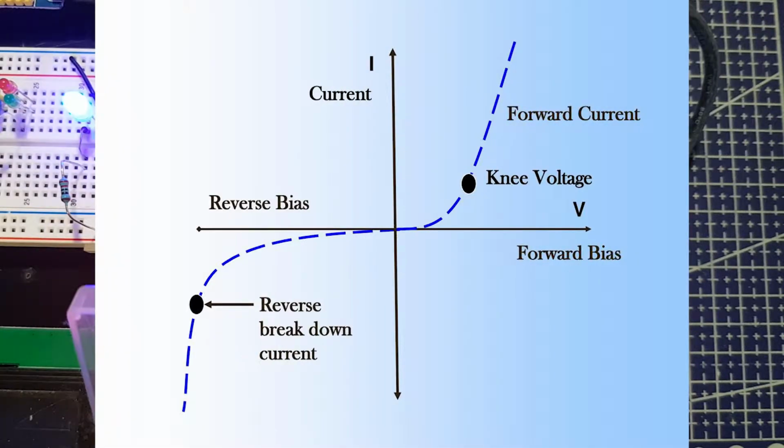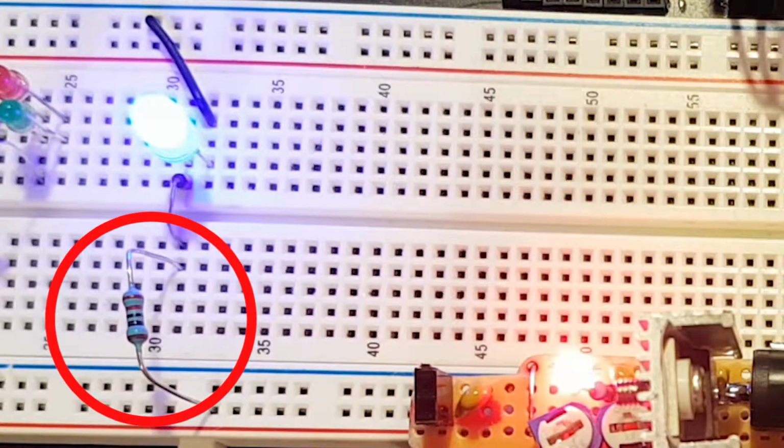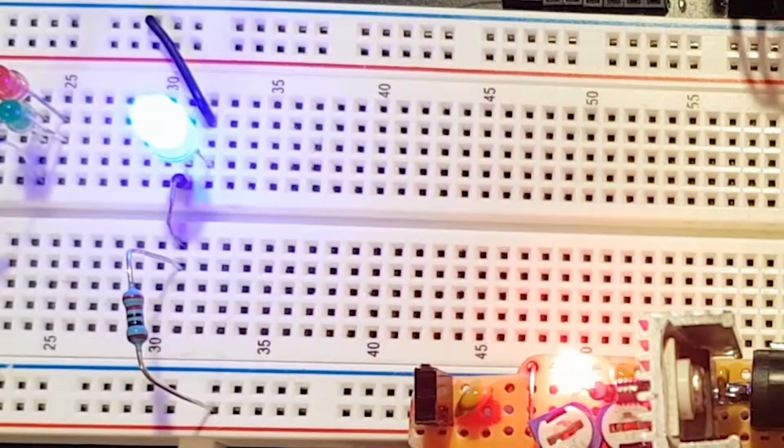This is not a linear relationship as in Ohm's Law, but a sharp curve. As you get past the knee, the current rises very quickly in comparison to the voltage, and the LED will melt or explode. To this end, you have to use a current limiting resistor. Most small LEDs, from 3 to 5 to 8 mil, are usually rated for a maximum of 20 milliamps, but just check the data sheet just to make sure. This is a maximum, remember, so you don't have to abuse them to get full illumination. In most cases with modern LEDs, 10 to 14 milliamps is plenty.